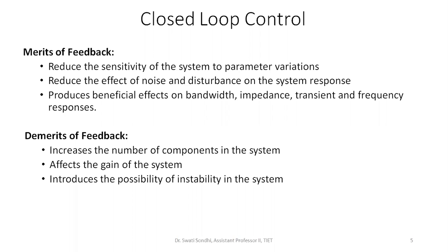It increases the number of components. Of course, you need a sensor, and it has to be connected in feedback. It affects the gain of the system. Gain means the driving power of the system, because when you add additional components in feedback, some of your energy is wasted in driving those components.